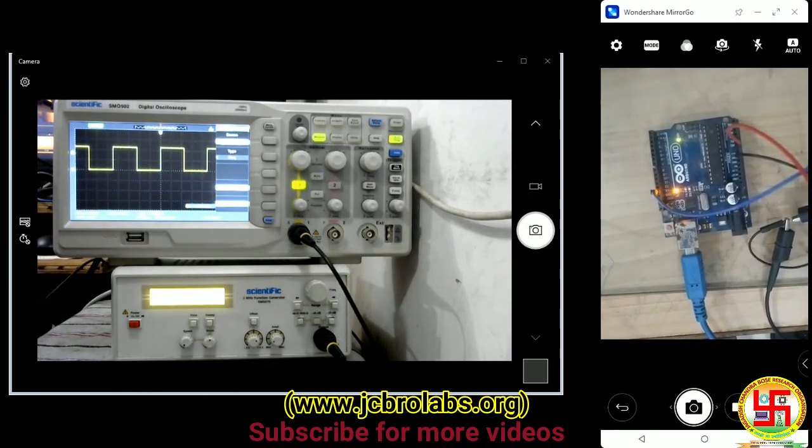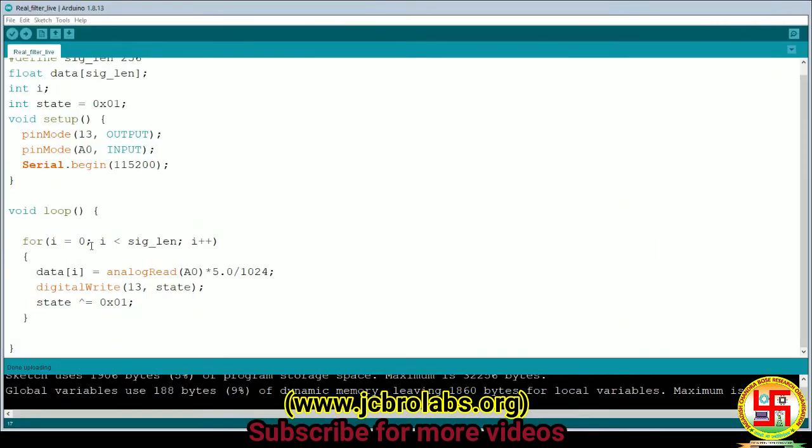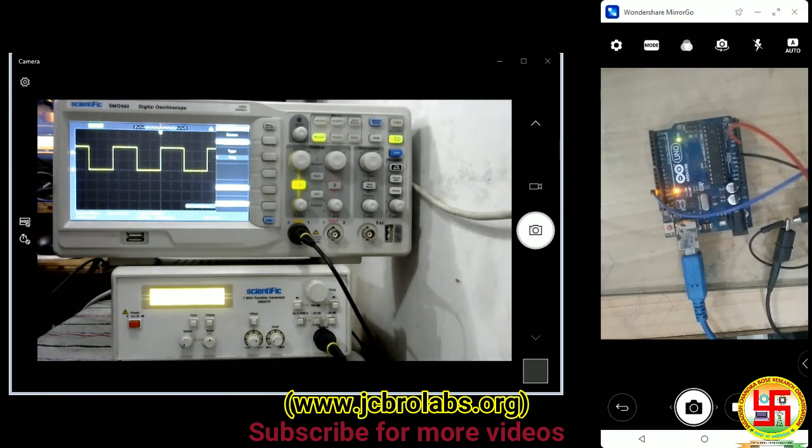Here it is saying 4.46 kilohertz. So this square wave frequency is 4.46 kilohertz, which indicates, if you see the code properly, that pin number 13 is toggling at every instant when data is taken. So if we are getting a frequency of 4.46 kilohertz, that means the data is being captured at double of that. Just keep in mind or try to understand it. The data is being captured at double the rate of this toggling clock. Right now this frequency is 4.46 kilohertz.